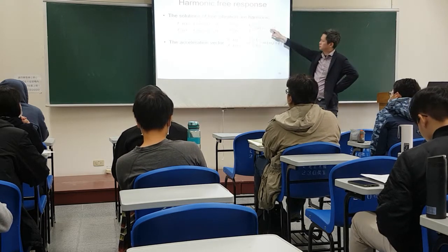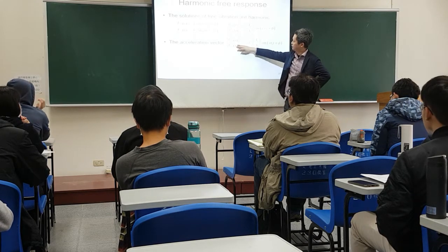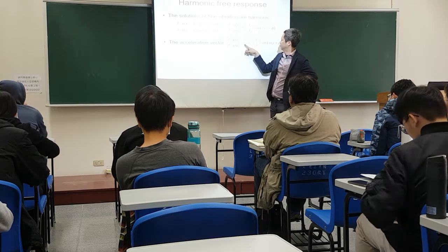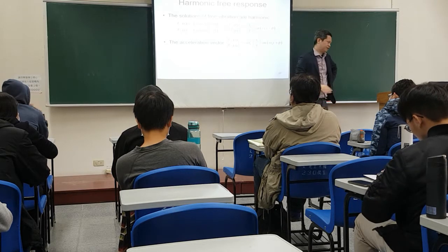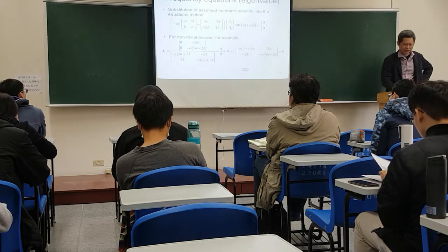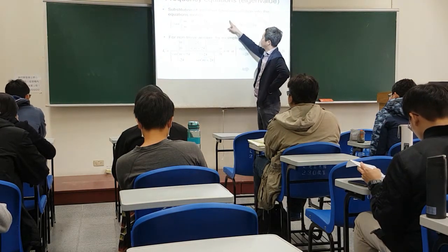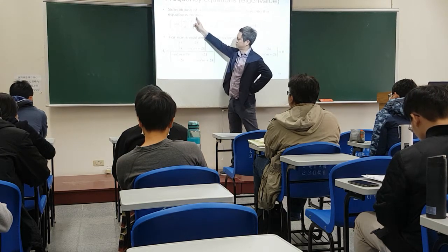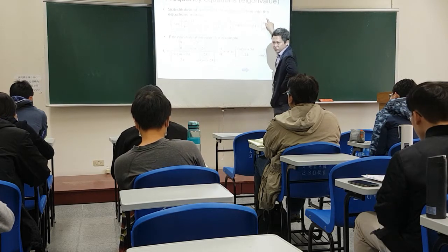if you do the substitution of the harmonic displacement, and then differentiate to get the acceleration, you find that the acceleration is actually minus omega n squared times the displacement vector. So in this way, when you do the substitution back into the equations, you have this simple form of equations with a common factor of amplitude times sine. What is inside here is your system matrix. In this equation, clearly you can see the right hand side has zero force.